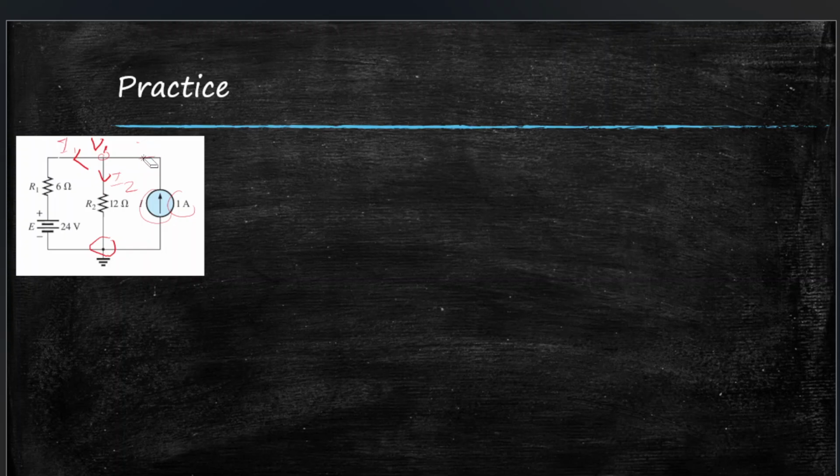We cannot assign anything here because the current source is already assigned here. The direction is already given upwards, this way. So that means this current source is entering the node. So when current sources are given, their direction will be followed as it is given, whether upwards or downwards, exiting or entering. But for every other branch, we will consider that the current is exiting the node. This just makes life easier.